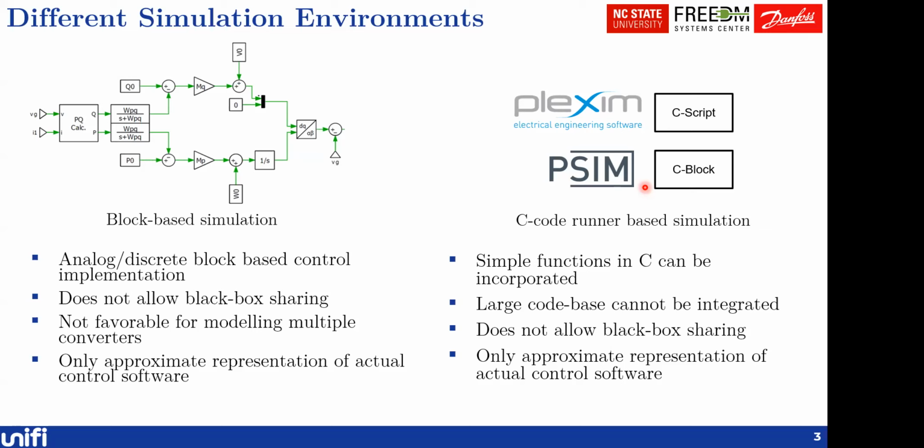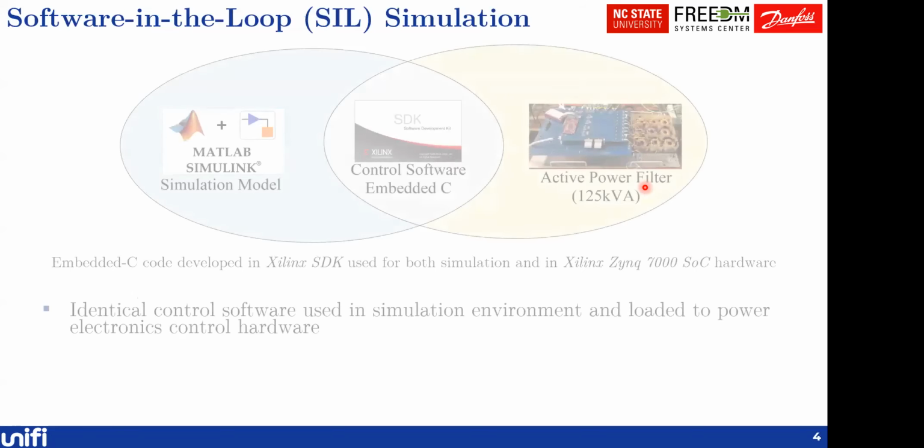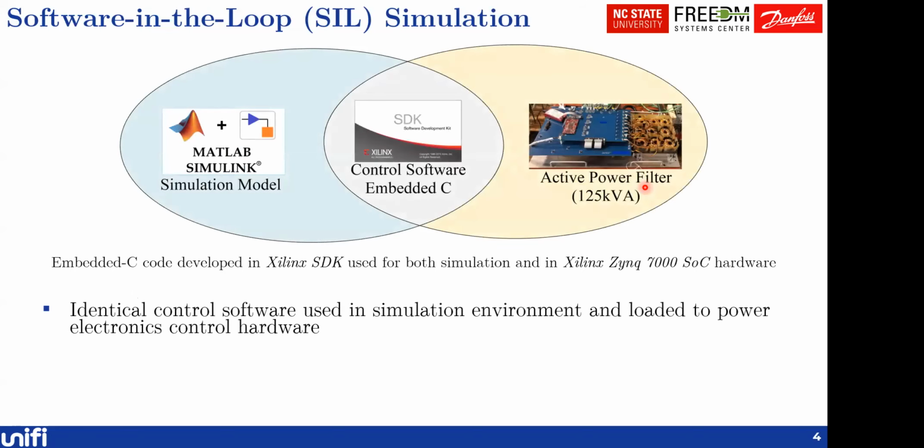All right, so then what SIL does for you is that the same software files, or the same software code base, that you are using to program your control hardware in your actual power electronic system, you can use the same files to run your simulation. So that's what SIL environment is.